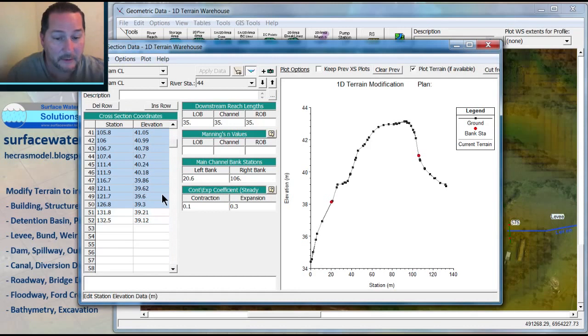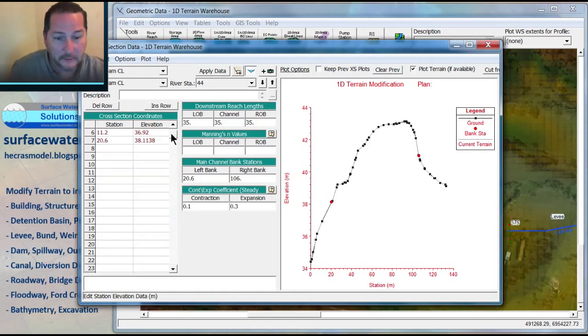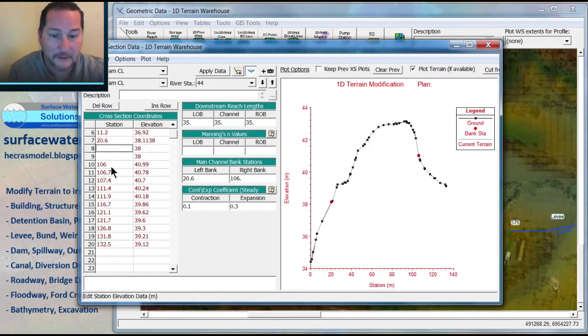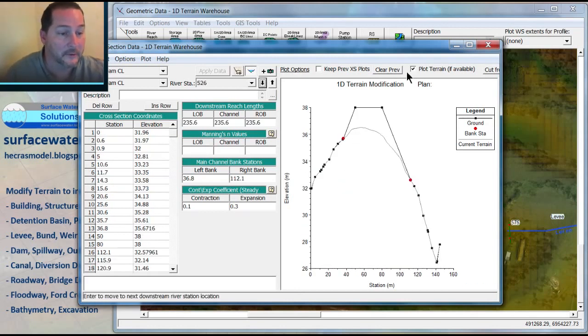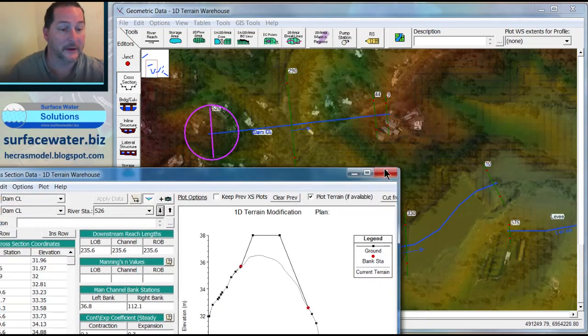So I'm going to come back out here to my end bank station, blow these out, and put in a trapezoidal dam that's going to be at an elevation of 38. In this case, that's below ground. I could have this thing sloping a bit, but let's come up here to 50 and 80, and now I've got a section there. And what you'll see then is that this is going to gradually transition back to the road, to the elevation of the existing ground right here.